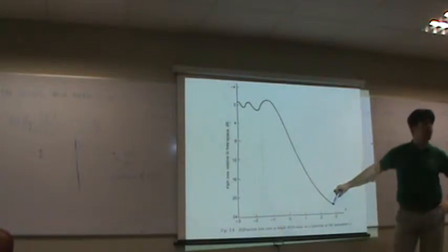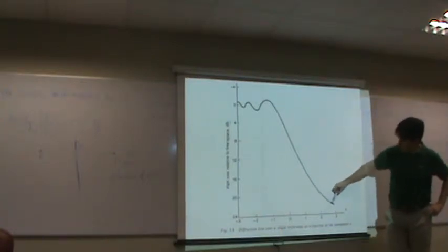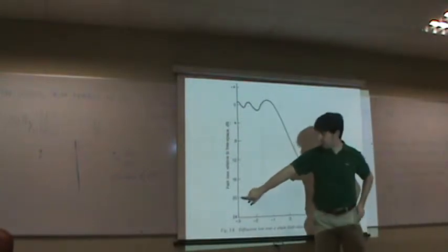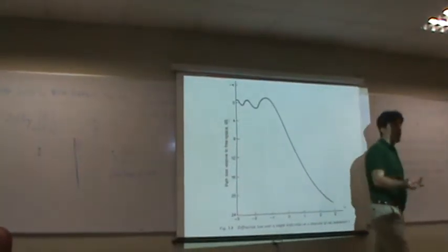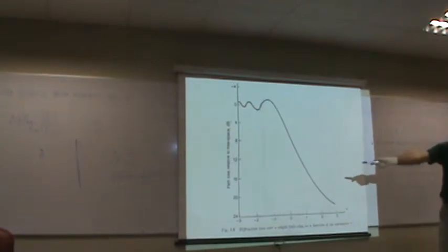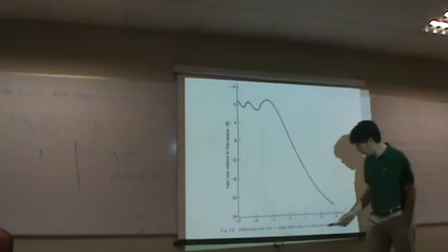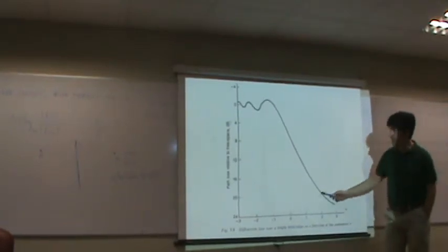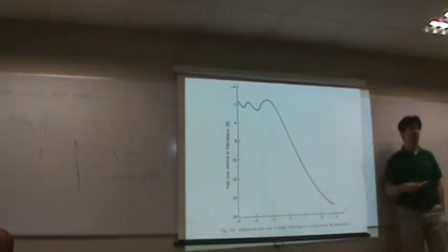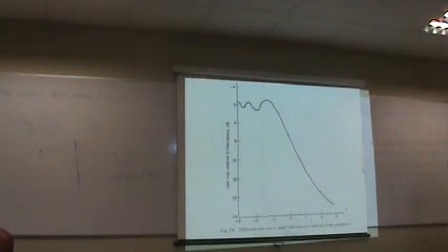But the field does not go to zero abruptly. You still get, with not very large attenuation, we are talking 16, 20 dB, this is 24. So even if the obstacle is higher than the baseline, you can quite often make the radio link.